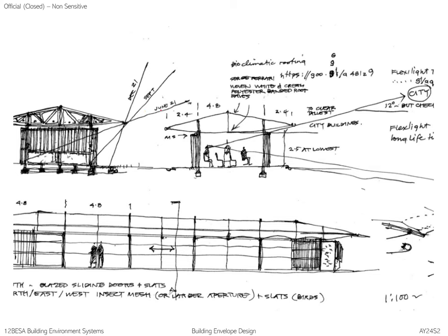Let's say on 21st of June, 4th of September, respective quarters, and 21st of December, at what particular angle the sun is hitting these particular locations. With that, he's able to establish the width of the roof eave, and the precision of that tip ties in with the precision that he knows the sun path. So he's able to control it. With this line, June 21st, I know that it's going to hit right up to the edge of the inner space. September 4th is going to just enter. It's going to cover the entire veranda space, but it doesn't hit the interior space yet. Whereas for 21st of December, it is excluded.